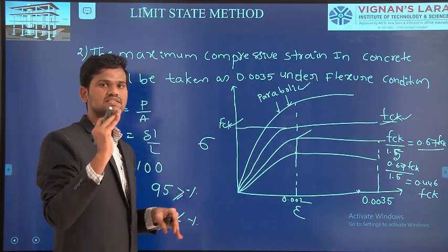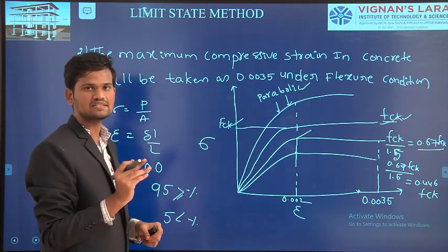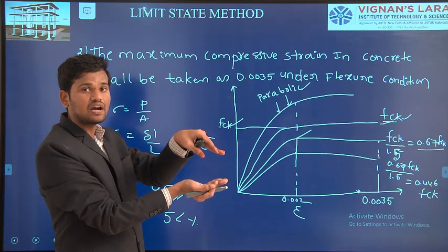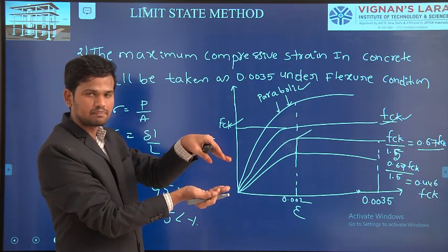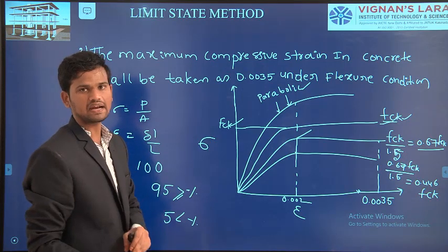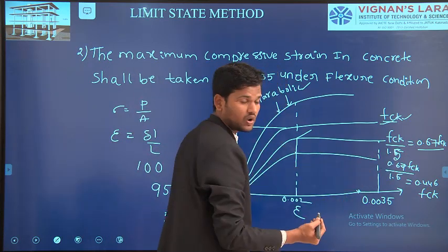Whereas for designed structural members in practice, if you observe any beam, slab or column, we don't have any such supporting members. Hence the strength of the concrete you test in the compression testing machine won't be obtained in the practical field. Hence we are introducing one term, 1.5.